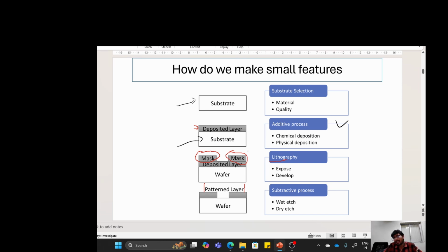These high-K dielectrics like HfO2 are desired for better performance of the devices. But there are some other drawbacks as well, like gate leakage, gate dielectric breakdown, and dielectric leakage currents.